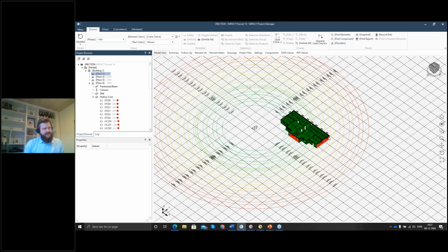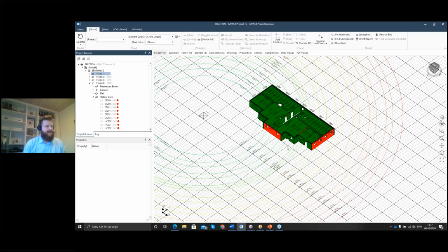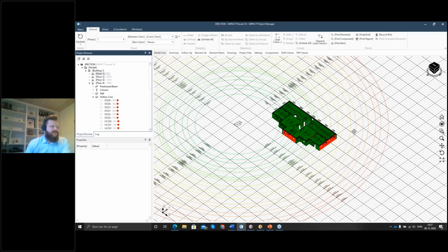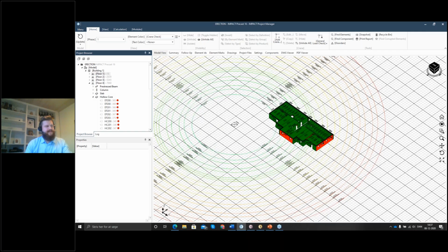So you can see here that some of the elements are red, some are green. Green means okay for this crane. Red means not okay. Either they're too heavy or they're too far away from the crane, which basically gives the same result, or if it's completely outside the element, of course. So if I want this crane to be able to place all the elements, of course I need to move it or put in another crane that can actually carry these.